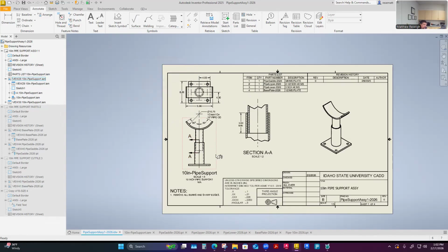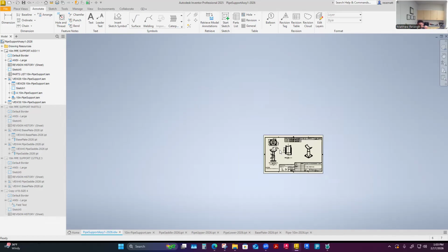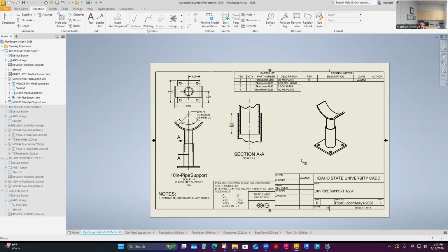It'll relabel the actual section view labels. So in my case, AA is what I would start with. I'd be interested if I do another one whether it goes to BB next or CC. I don't know, I'm not going to worry about it. That's why I think we wouldn't worry about it: it can become a little domino effect of relabeling and maybe mislabeling things. I'll just let it randomly pick another. If my first section view is CC, as long as it's not named like anything else, roll with it. They're just identifiers. So that's how I would change that.